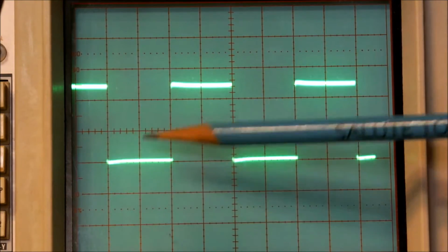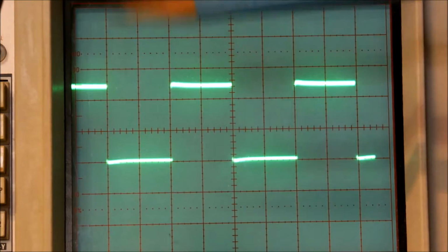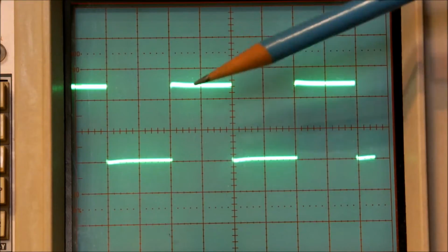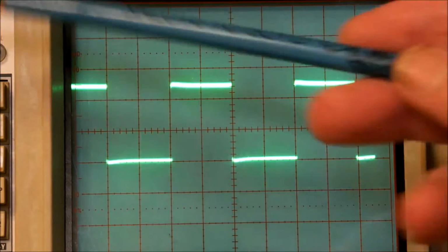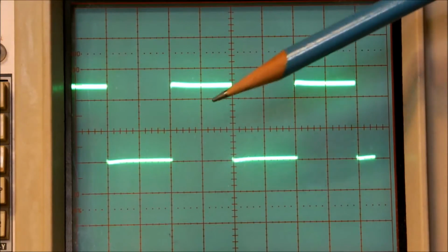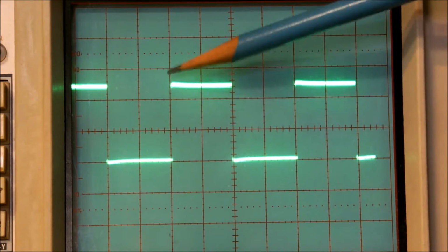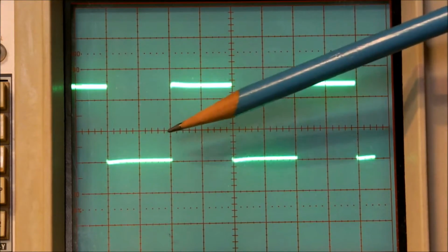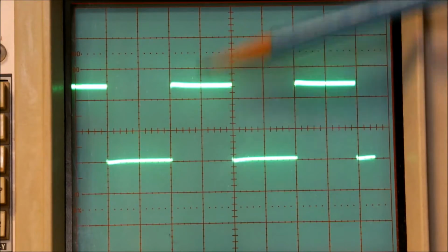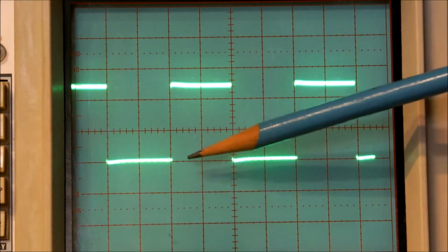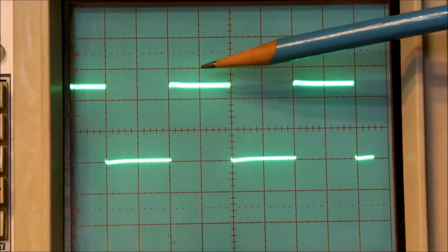From the lower trace to the upper trace, we're representing the voltage of the signal. Each one of the little squares or gradations is worth 2 volts. And you have a knob over here to set that. You can vary that. But if we count those up, we've got 2 volts here, 2 volts here, and about a half a volt here. A little less, but close enough. So we've got 1, 2, 3, 4, 5 volts from peak to peak. That's called the peak-to-peak voltage. From a minimum of 0 all the way up to our 4.8 or 5 volts.